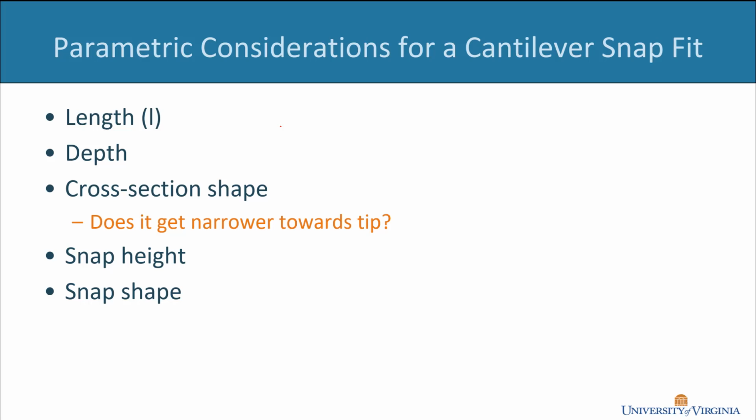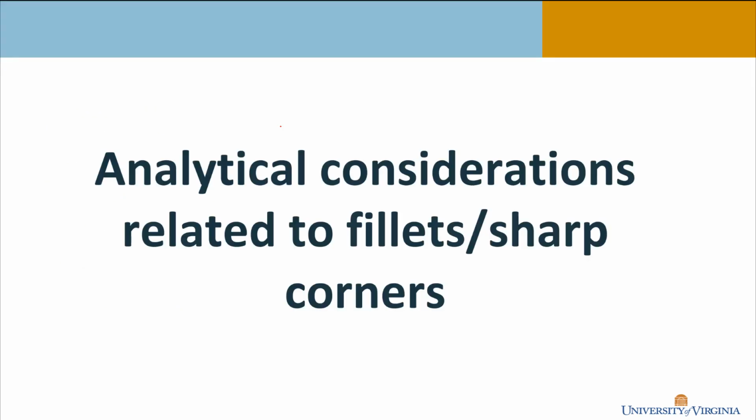And with the idea that, so certainly the material is a consideration for design also, but in this case, you're using a PLA 3D printed material. Another important consideration is that you need to avoid, if you can, any sharp corners in your parts in any areas that have high stress.